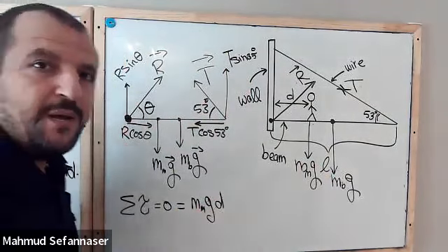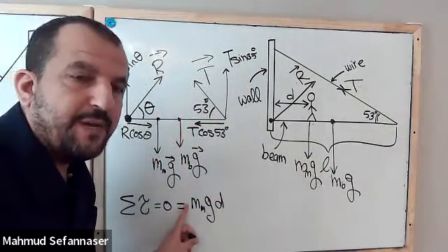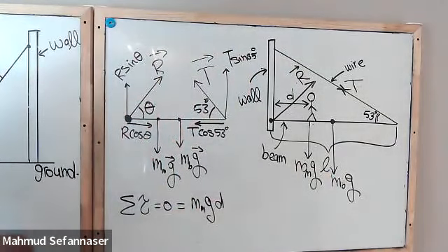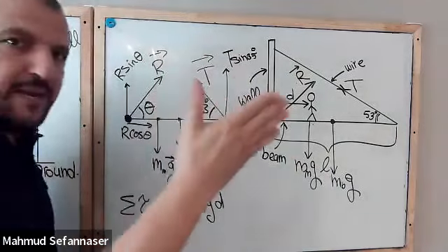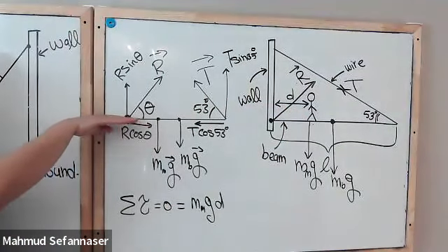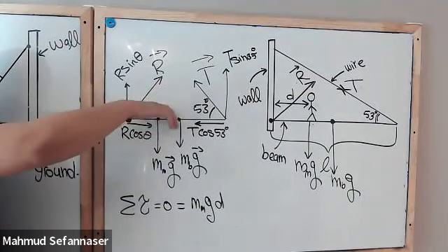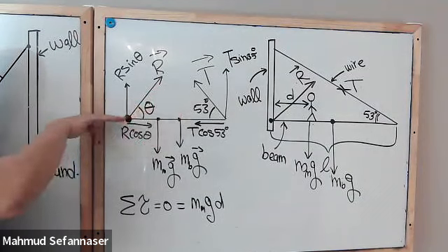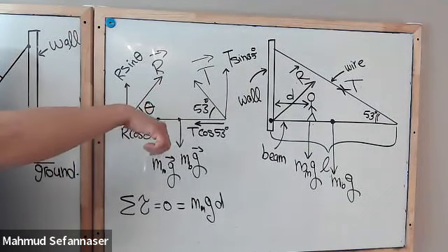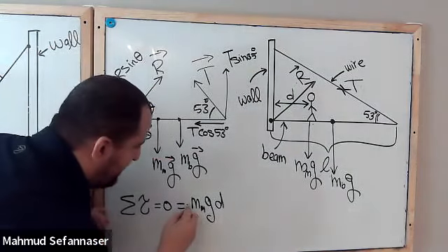Now we need to have force, which is mass of the man times gravity times the distance D. So that will give me the torque. But what is the sign here? We need to think about the sign. Again, guys, apply the same idea, the right-hand idea. So we have D going in this direction. So D cross weight, that will give me torque into the whiteboard. So we need to have a negative sign here.